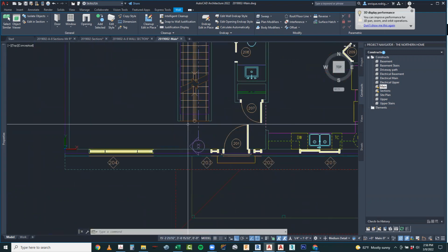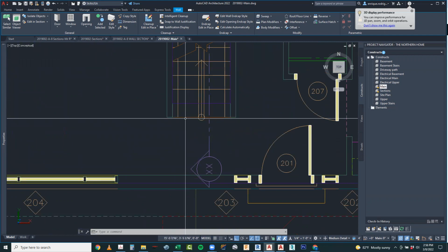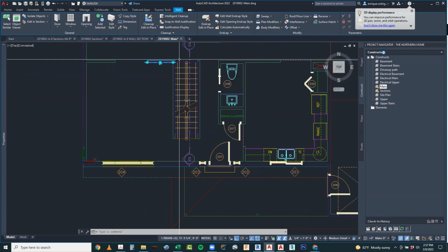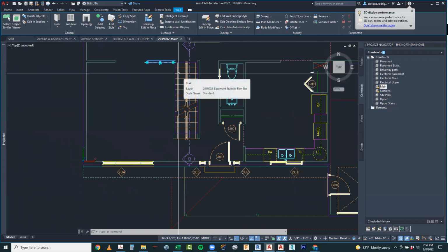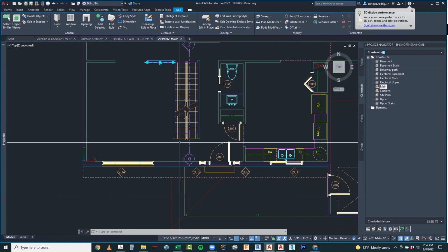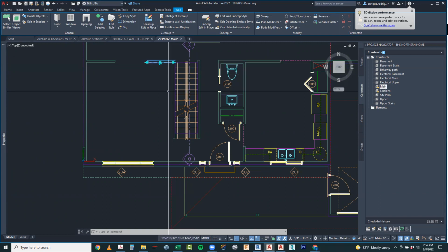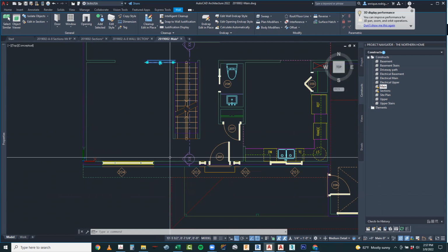And our first riser is going to be right here at the bottom. The big questions are, we know what our vertical height is. Everyone's going to have the exact same vertical height floor to floor. It's 9 feet. Converting that to inches, it's 108 inches. What we all may have slightly different, because you've all modified your plans a little bit, is your horizontal distance or your run of your stair.